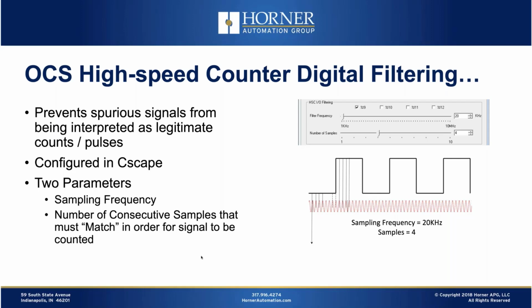So generally in most high-speed counter applications, you have a certain frequency in mind or a certain period in mind or pulse width in mind when you set up the application. You know that regardless of what happens in my machine, I'm not going to be getting legitimate pulses in, let's say, that are more frequent than every 5K or more frequent than every 50K. So by understanding the width of legitimate pulses, you can configure our digital filter in the high-speed counter function to accept all those legitimate pulses and signals, but reject the ones that are just maybe short impulses that don't belong.